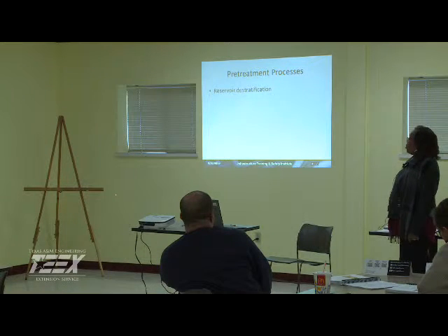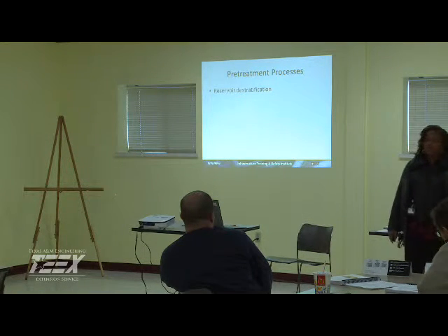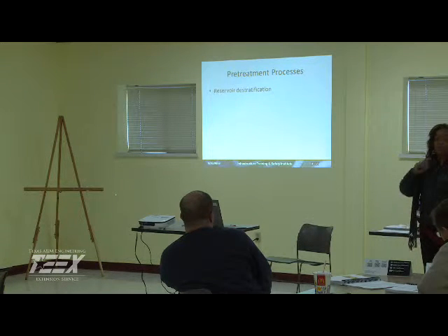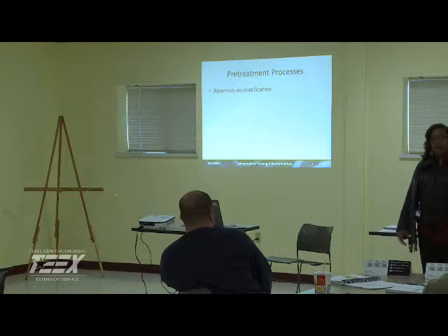Now, with pre-treatment, we may do something as simple as lake destratification, because when you have the various seasons, you have warm water, you have cold water, and when you have those stratified lakes, you can produce things like taste and odor issues, hydrogen sulfide.